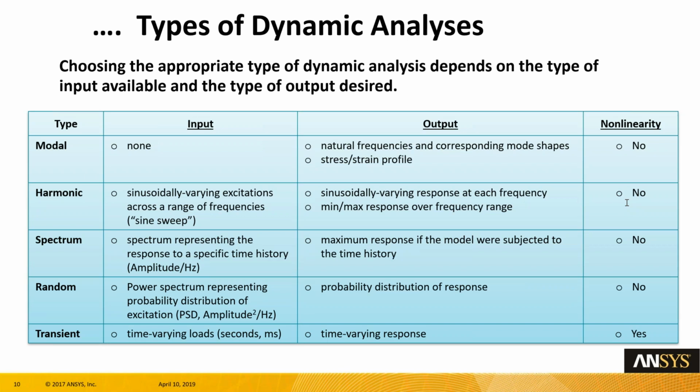And on top of that, if you specify a global damping value, that will also be cumulative, meaning that now you have mass damping, you have stiffness damping, and then you will have global damping. One thing is you may want to make sure you're not damping the structure a lot. So you may want to check on your damping values.